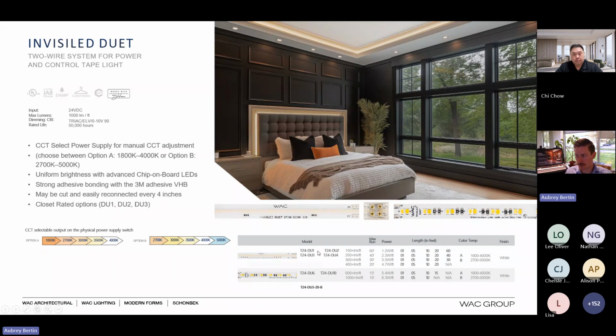And we offer it in 100 lumens, 200, 300, 400, 600, or 1000 lumens per foot, which is an awful lot of lumens per foot. And again, that's over 2 wires. So you can do this in a retrofit situation. You don't need to run new 3-wire, 4-wire, 7-channel tunable white anything. You can do it over 2 wires, and that's what makes this particularly unique.